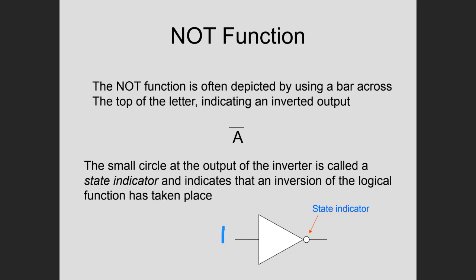That's that digital pulse, that positive going digital pulse. And it's a pulse if we're going to move it. And so when that 1 moves into this gate, it's still a 1. But I want you to think of when it hits this bubble, the job of this bubble is to change it to the opposite bit. So when that 1 hits this bubble, then it becomes a 0. So over here, you got a 0. Or when this is a 0 over here, when it hits that bubble, it changes to the opposite bit.